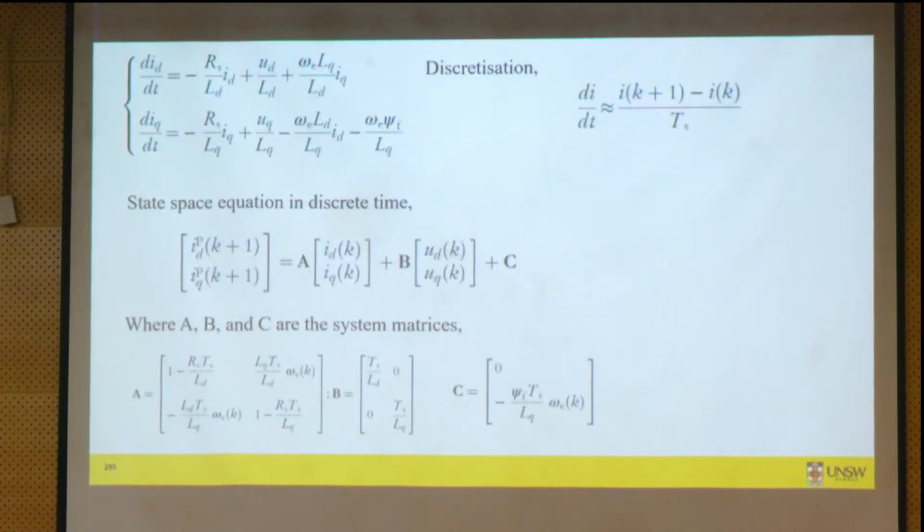If we look at its implementation, we start with our DQ equations, but we can write those dynamic DQ equations as state space equations. We can then discretize those equations, especially the differential terms, because MPC can only operate under discrete conditions.